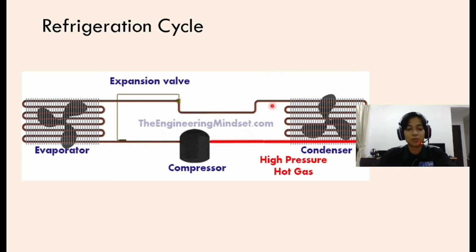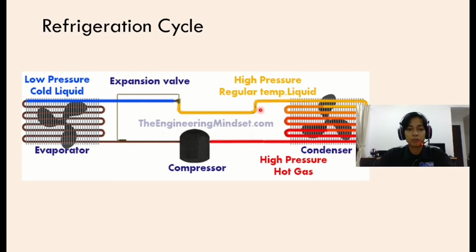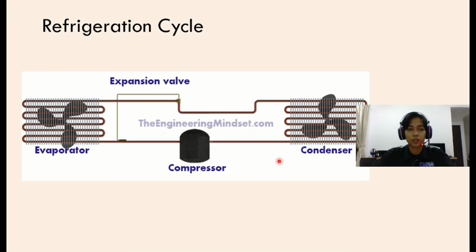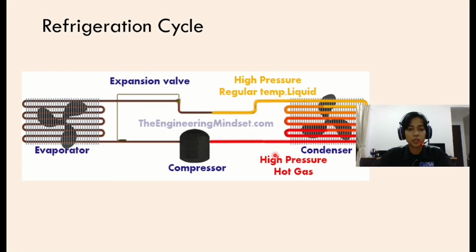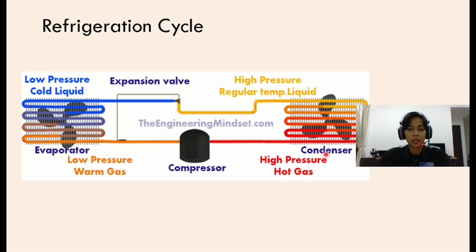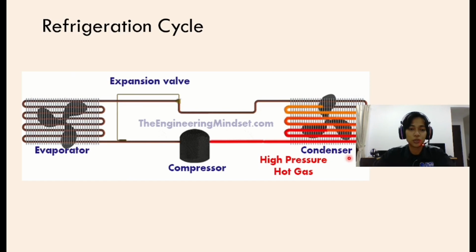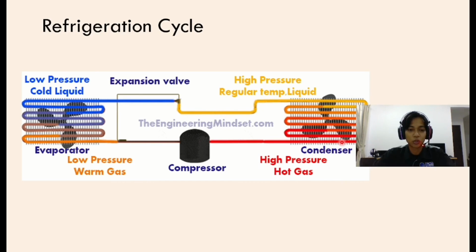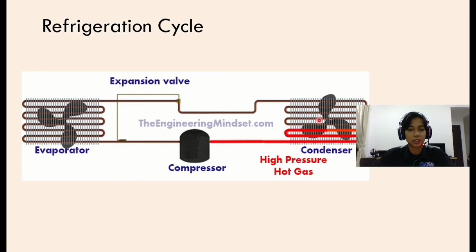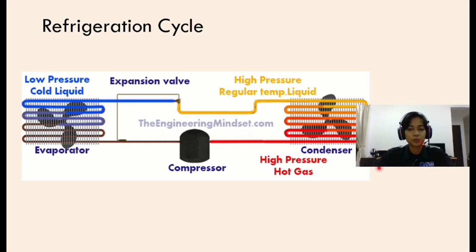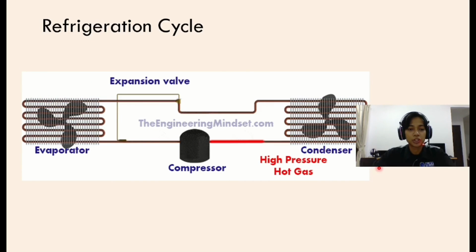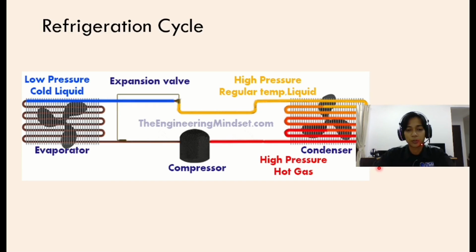Next, I will explain about the comparison of inverter and non-inverter air conditioners. The key difference between the two air conditioner types lies in the compressor's ability to regulate the speed of its motor to adjust the room's temperature. Once a room is cool, inverter air conditioners lower the speed of the compressor motor to save energy and refrigerant required to cool the air.